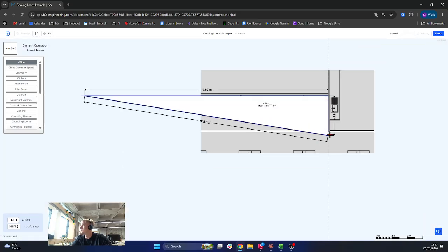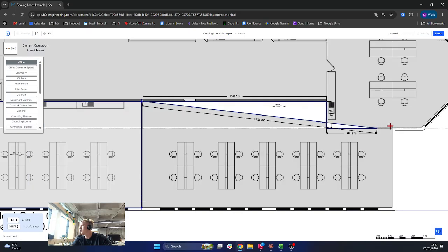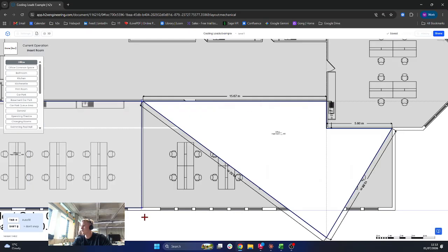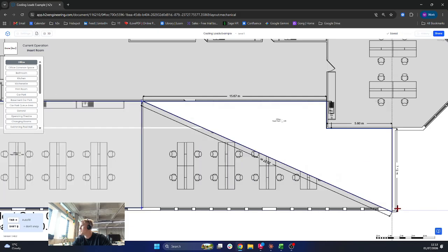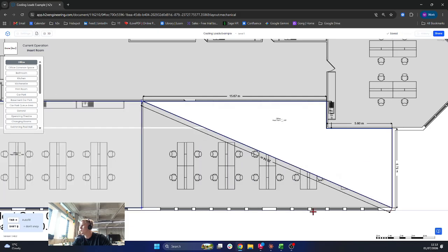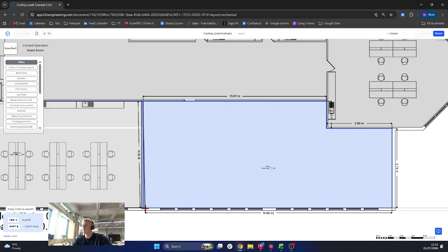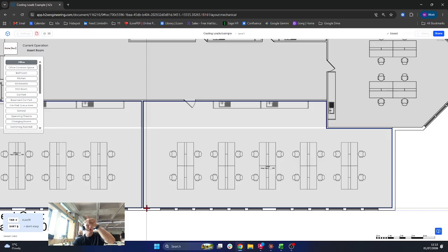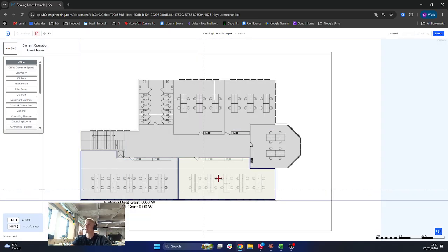left click here, here, here, line our mouse over there to begin with, and then that'll give us our alignment point. You'll notice when we are drawing rooms, we are drawing the circumference, so we need to go either clockwise or anti-clockwise around that room.